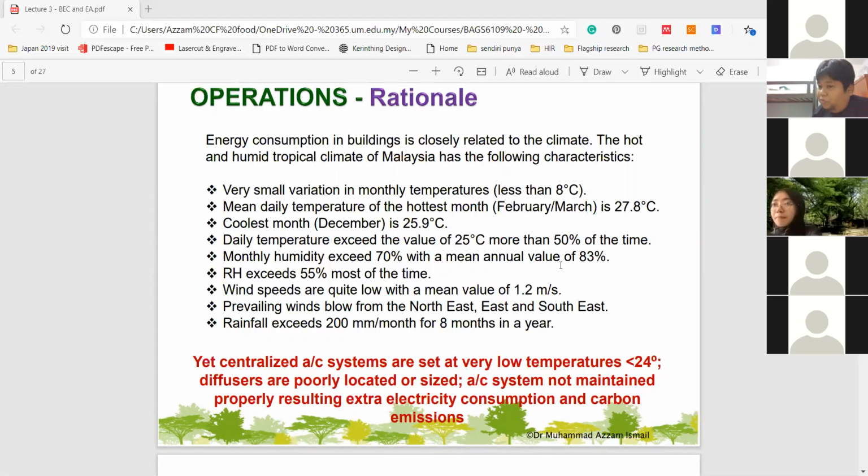So your roof becomes really important. You have to insulate your roof. If you use a certain material for your roof, let's say clay tiles or cement tiles or metal deck or whatever, you have to insulate them underneath to make sure that the roof performs better, right? If you don't insulate, you will allow a lot of heat to go in.